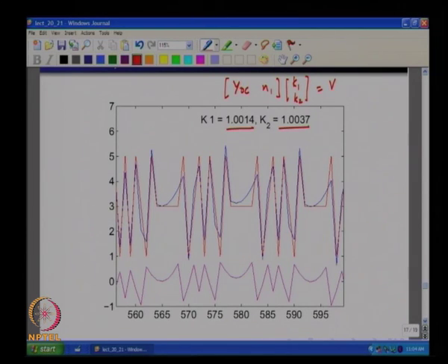I mean, see, please note that when the input is 3.1415, are we saturating the quantizer at all? The quantizer steps are from -7 through 7 with deltas of 2. We are well within the linear range of the quantizer, and this is a second order delta sigma, right. So the variance of the noise is not too high, correct. So we are not presumably saturating the quantizer, right.